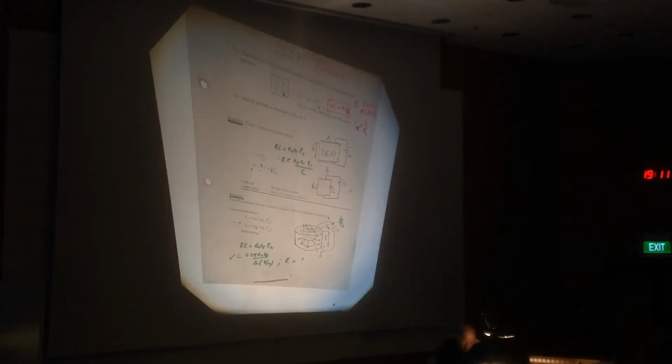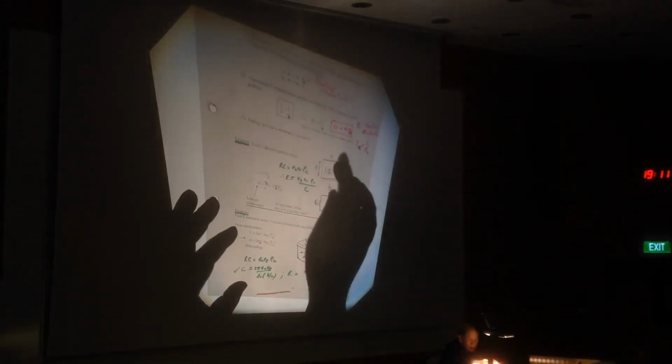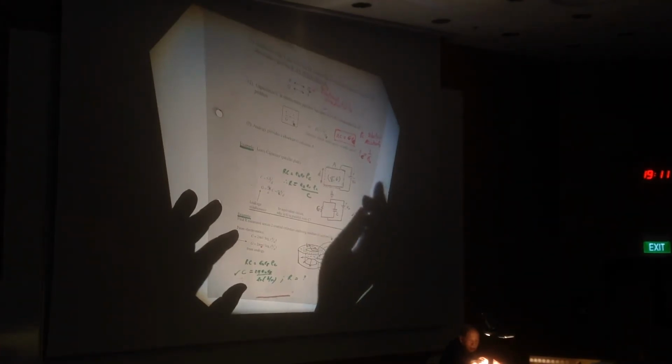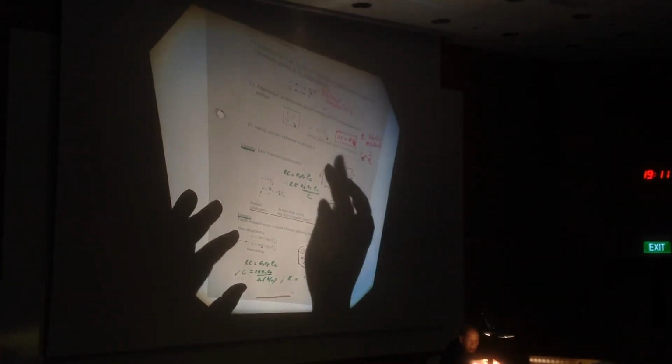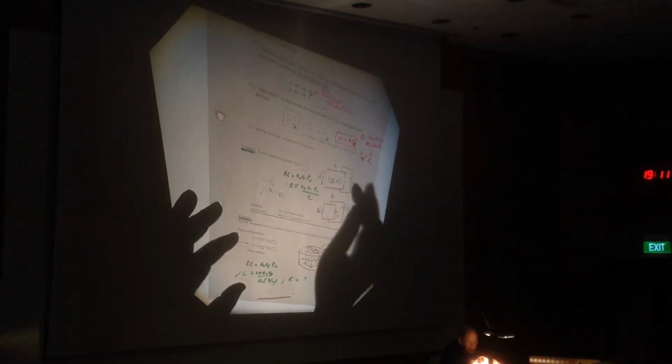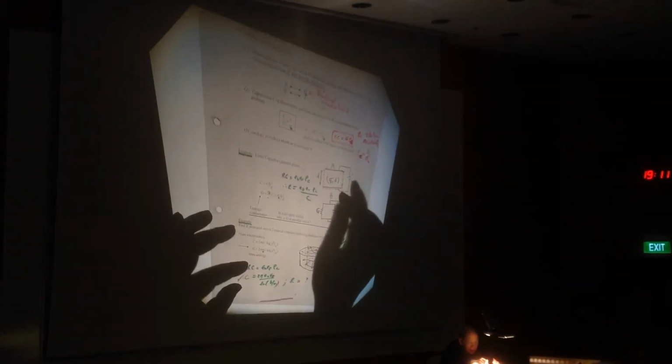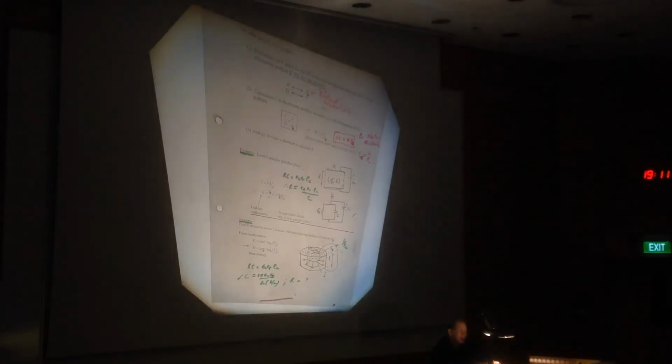In this case you can calculate how long it takes. You have a lossy capacitor, you are given sigma C, you have epsilon, the capacitor plates and the capacitance, and you are asked, the capacitor is charged up, how long does it take to discharge, say to half the voltage? It's a simple capacitor discharge problem. We know the exponential e to the minus t upon tau, and tau is the time constant. You know R, you know C, and everything can be found out. No big deal, right?